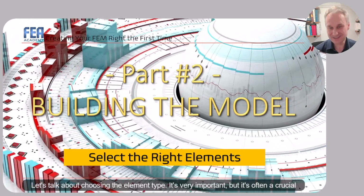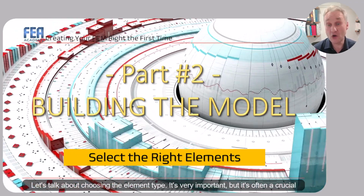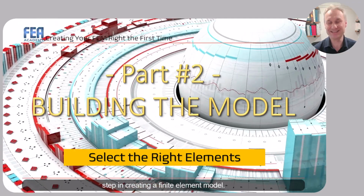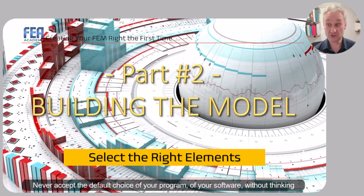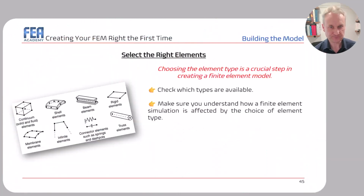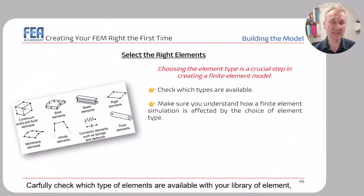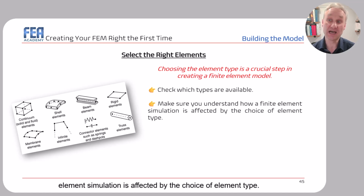Let's talk about choosing the element type. It's very important, and it's often a crucial step in creating a finite element model. Never accept the default choice of your program, of your software, without thinking about it. Carefully check which type of elements are available with your library of elements related to the software you're using, and make sure you understand how a finite element simulation is affected by the choice of element type.